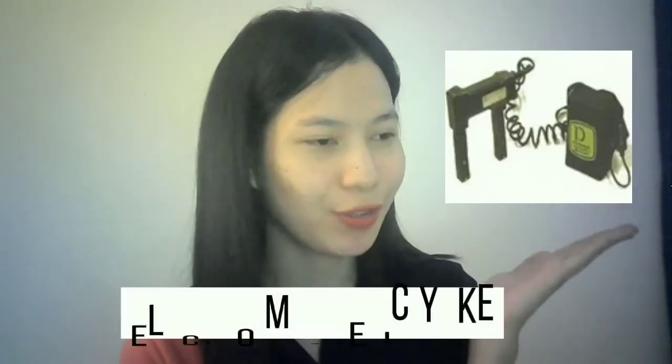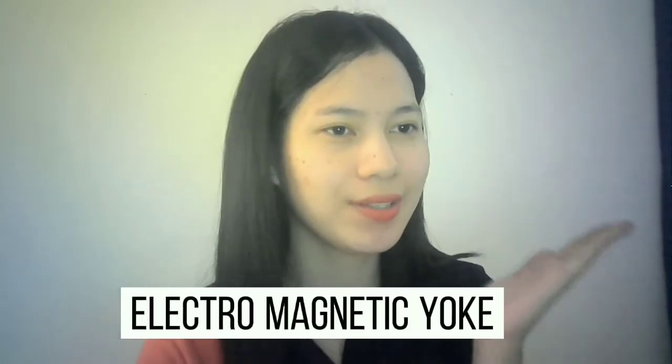The second equipment I will be discussing is the electromagnetic yoke. This yoke is a very common piece of equipment that is used to establish a magnetic field. A switch is included in the electrical circuit so that the current, and therefore the magnetic field, can be turned on and off. They can be powered with alternating current from a wall socket or by direct current from a battery pack. This type of magnet generates a very strong magnetic field in a local area where the poles of the magnet touch the part being inspected. Some yokes can lift weight in excess of 42 pounds.